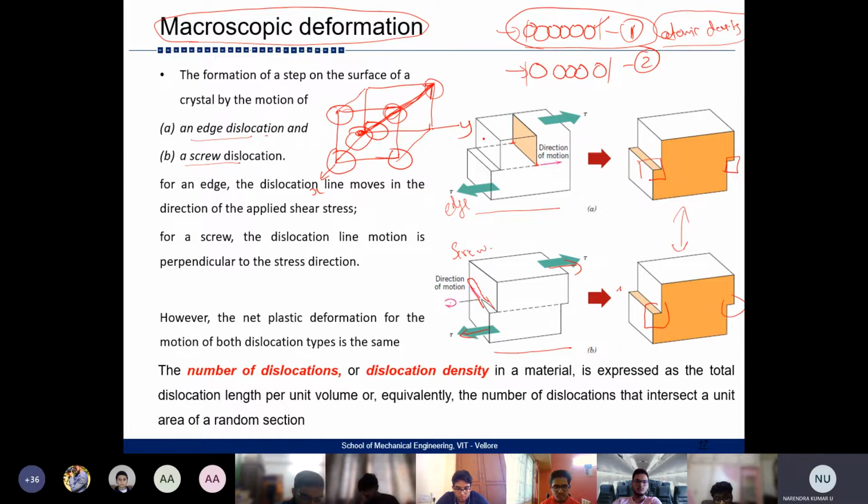What is this direction in Miller indices? 0, 1, 1, right? If you see this particular direction, 1 atom, 2 atoms, 3 atoms. And if I have this one, 1 atom, 2 atoms. So in this, the slip will occur. That means any stress or load applied at this point can easily move along this one rather than this one. This is how it is going to happen.